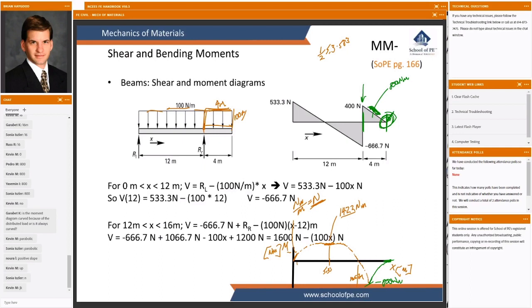Now, our transition from the free body diagram to the shear diagram follows exactly the same rules as our transition from the shear diagram to the moment diagram. So if we had a shear diagram that looked like this, then we'd have a moment diagram that had triangles in it. Where you see constant 0 slope on one diagram, your next diagram will have a consistent slope on it. So if you have a constant value here, you have a constant value for slope in the next diagram. If we see angled lines in this diagram, then the next diagram is going to be parabolic.